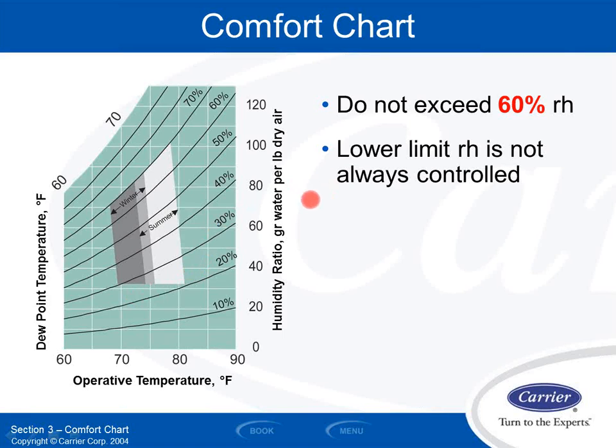There's no lower limit minimum, but I tend to want to be above 20, 30%-ish. So the box gets really, really small on where I'm trying to be with all this stuff. You shouldn't have summertime set points that are cooler than the wintertime set points on your thermostat. I go to facilities, people ask for that. Almost all cases it ends up getting traced back to oversized cooling equipment that's driving people to want set points below 75 degrees in the summertime.